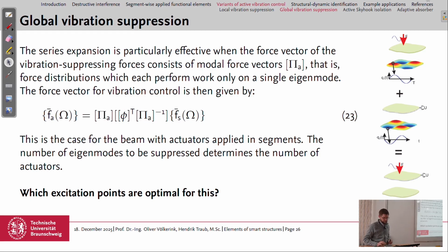So the force distribution that performs only work on one specific eigenmode would be a modal force vector, and it would not perform any work on the other eigenmodes.